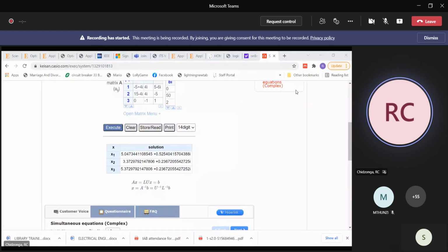And after you do a number of examples, you'll see that at a certain point, you will be able to write these matrices even without writing the equations. You look at the network and you will be able to write this A matrix, you will be able to write the B matrix, and therefore right away feed them into a computer package to calculate whether they are voltages or currents. And once those are determined, every other question you may ask or to find out about current flows, power, you will be able to calculate it. And therefore, you will say you have analyzed your circuit.